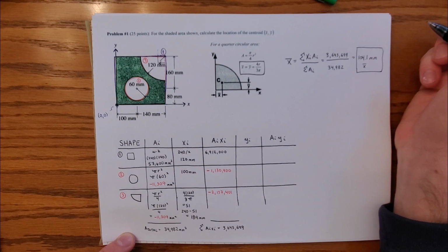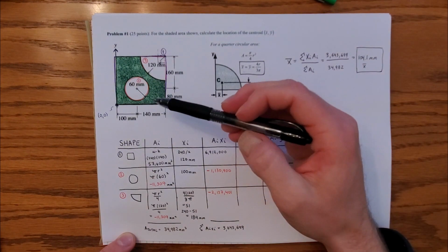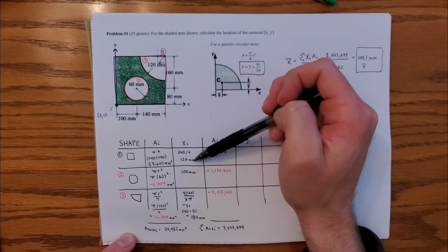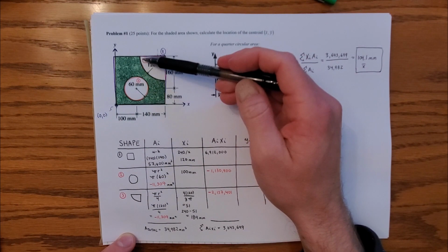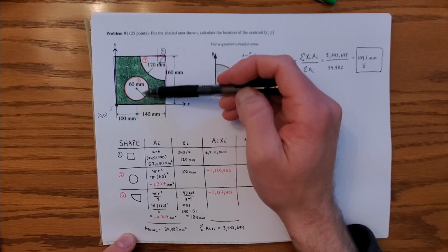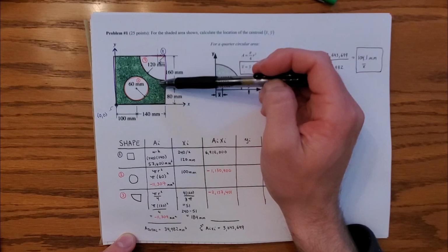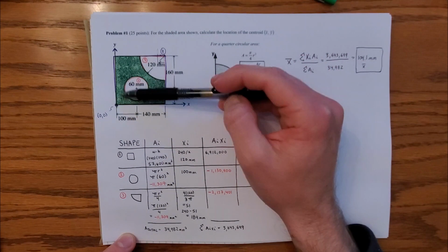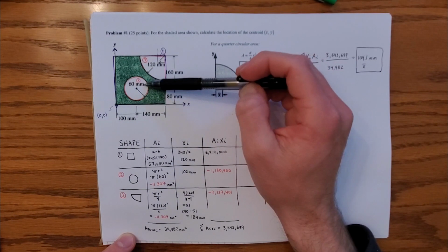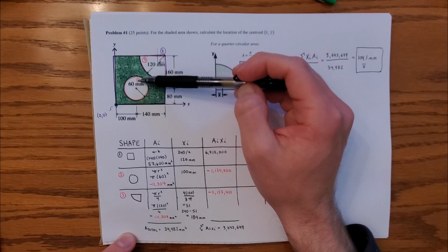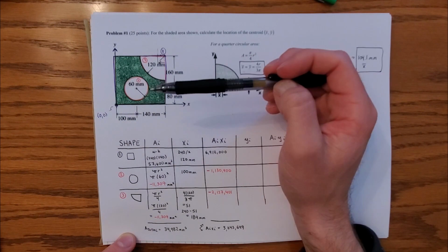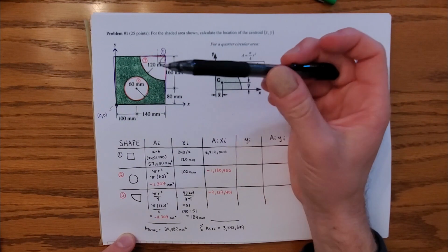And we'll just write x bar down here again, and we will circle our answer. Now, if we want to check our answer and see if it makes sense, I think it does, because if you look, our whole system right here, the middle is normally at 120. We've got this big old chunk of area missing over here, and we've kind of got more area missing even to the left. So as a result, we definitely have more mass closer to the left side than we do on the right side of this system. So our center of mass, it makes sense, one, that it's in the shape, and that it's probably a little bit to the left of the center where it would be normally.